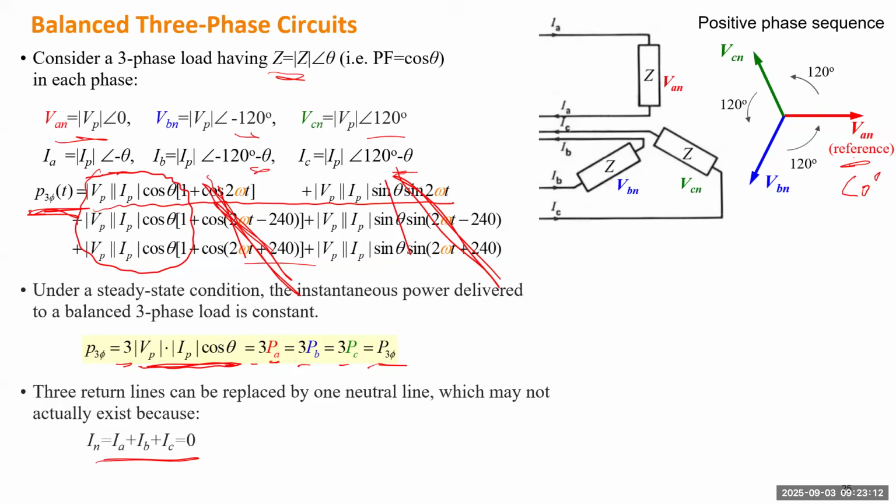So when we put the 3 currents together, they have to cancel out. Which means if we connect those 3 lines, we just short circuit those 3 lines, so the total current will be 0, which is equivalent to just removing this line. So just get rid of those 3 lines. Any question? Explain how you got rid of the sine algebra.